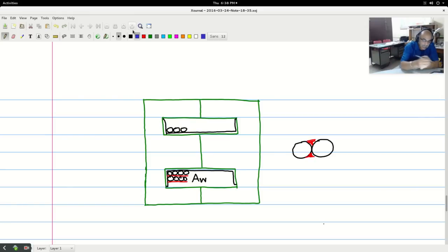So what you should understand is the whole window area is not available to you. There is a factor kW. Now kW is less than 1, and kWAW is the available window area. So it is much lesser than AW.